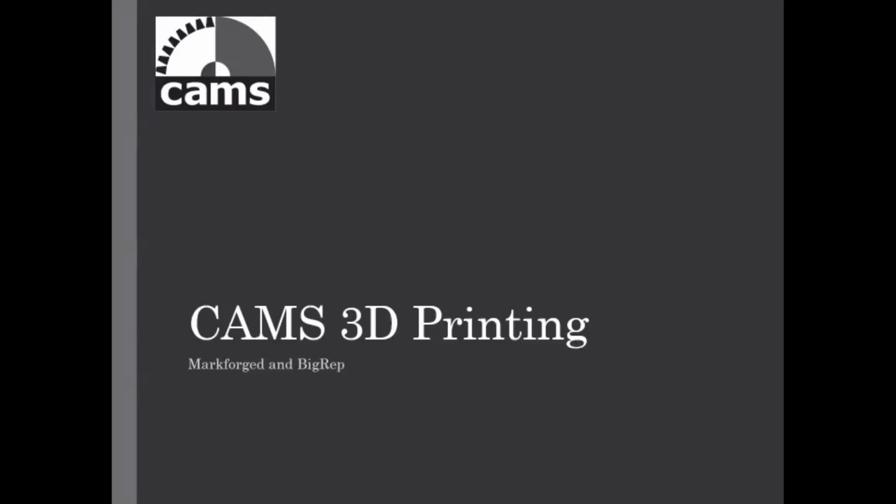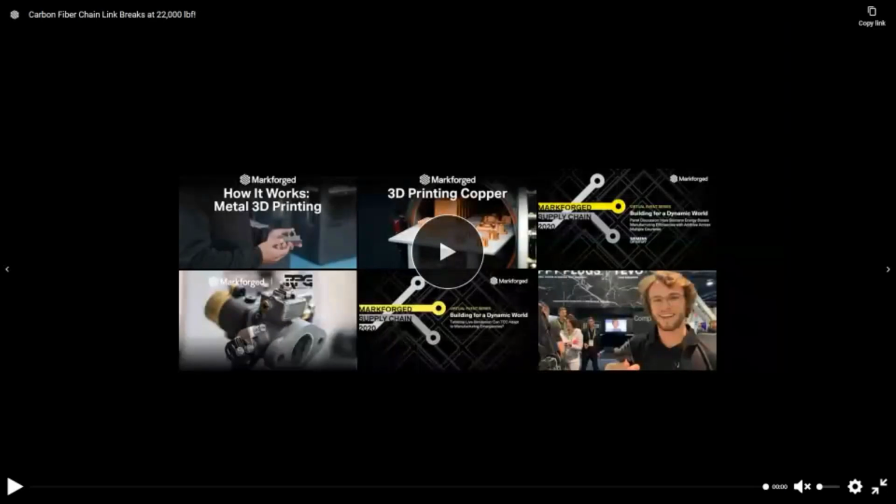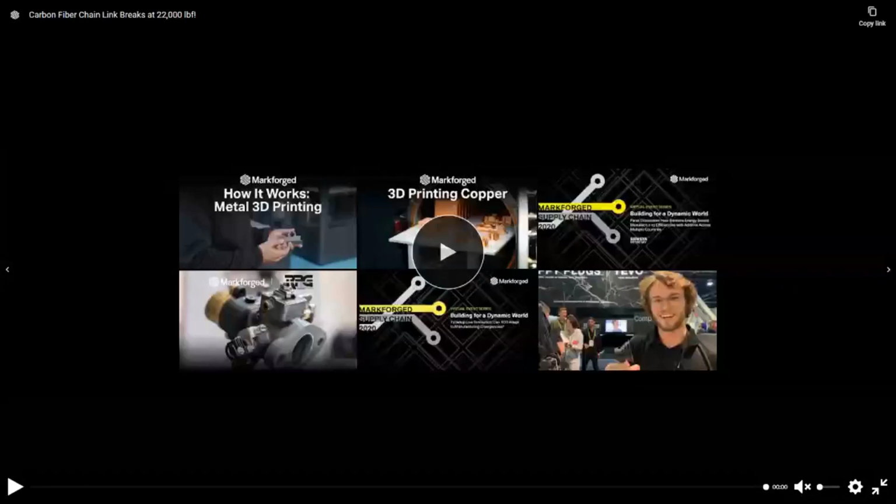First question is, on the PEC amount for drilling operations by percent of tool diameter or flute length options, does it output the percent entered as the Q value in the code, or does it do the math to convert the percentage to a distance in the code? That's a great question. It will do the math and convert from whatever the tool diameter is, from the percent entered, and change the Q value in the code to what that distance of the PEC amount would be. And likewise with the flute length, if you do a percentage of the flute length, it'll convert that automatically and change that Q value in your code accordingly to whatever that distance would be.